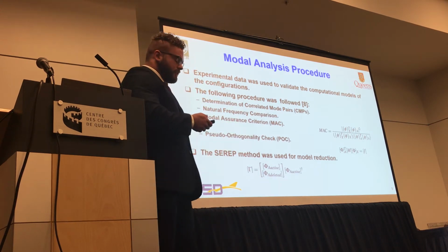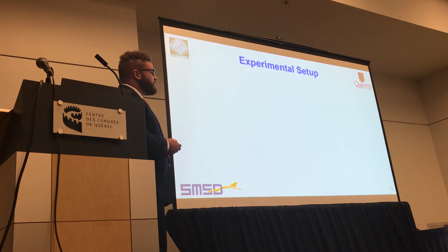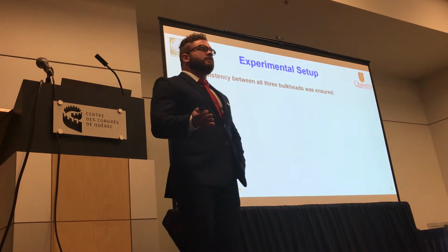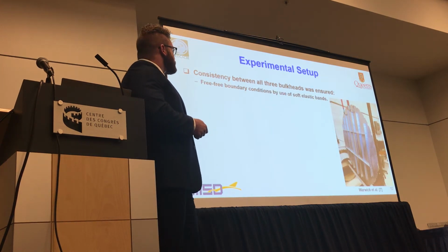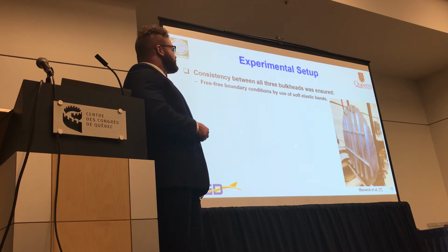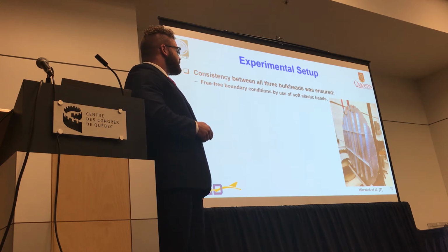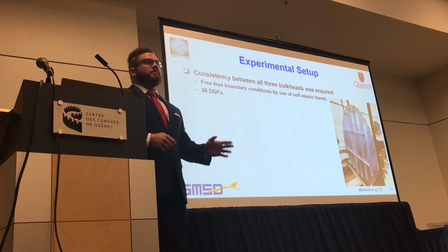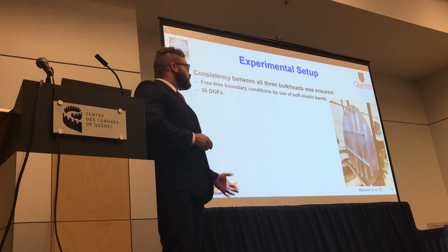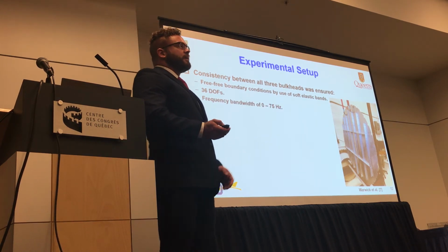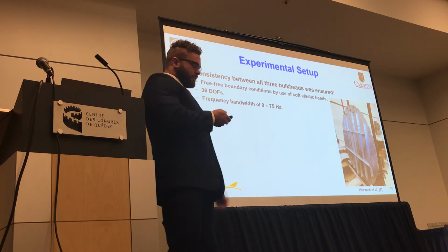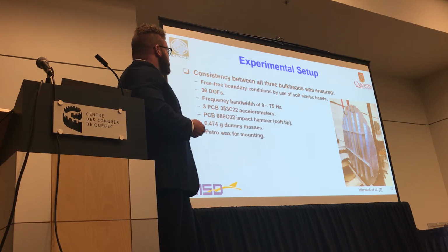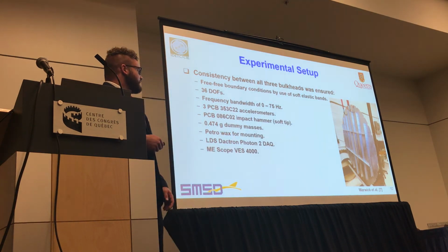of experimental eigenvectors. So for the experimental setup, I wanted to ensure consistency between all 3 bulkhead configurations, and I did so by applying the same boundary conditions. We simulated experimentally free boundary conditions by the use of these soft elastic bands attached with carabiners here. We used 36 evenly distributed degrees of freedom on the bulkhead on all 3 configurations. We analyzed a frequency bandwidth of 0 to 75 hertz just to give us enough modes to be able to validate the computational model. And then there's a little bit more detail about the experimental equipment that I don't really want to get into.